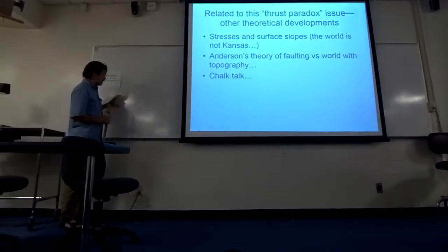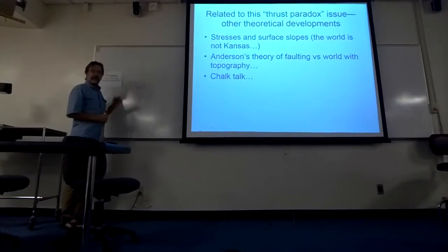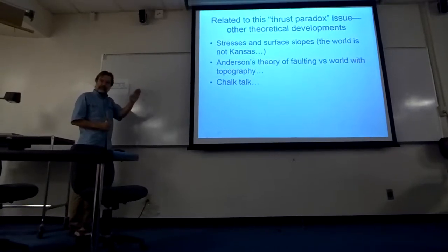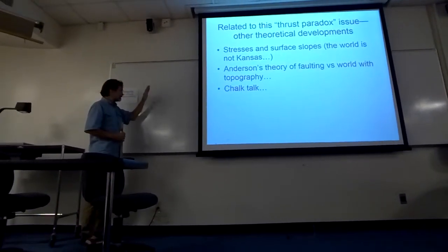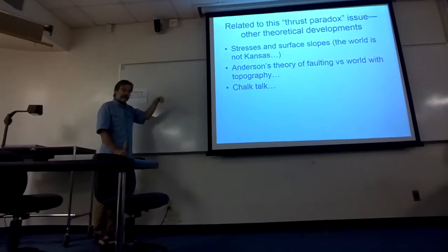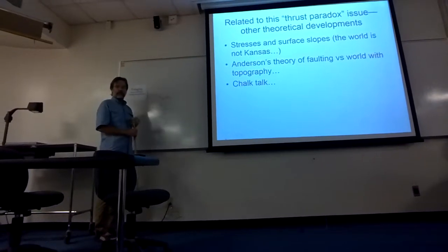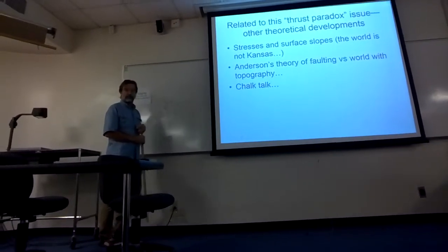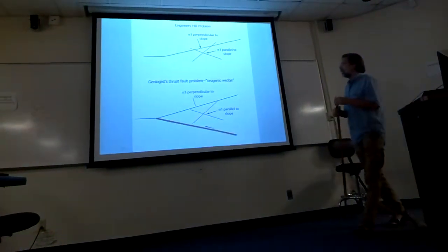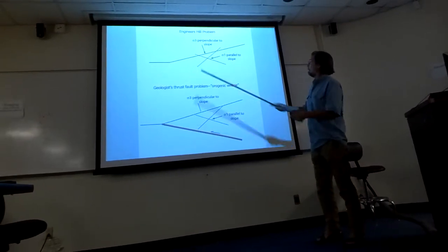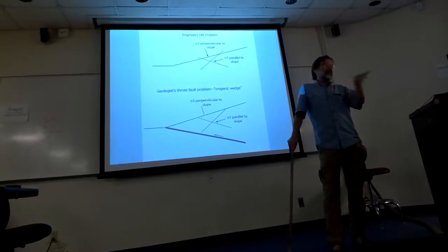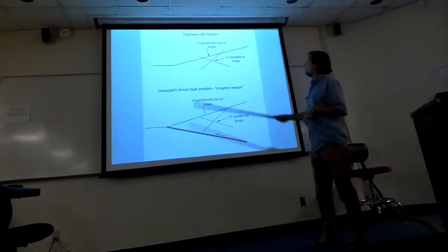One thing that we realized: when it's not flat, sigma v is no longer vertical either. So if you have a slope, the same kind of symmetry effect has to apply, that the principal stresses need to be, at least in the shallow part, perpendicular to the surface. But if the slope is there, then the principal stresses are also inclined. And therein lies the important part of that particular story, because the moment you make a surface slope, you're into the engineer's problem and not the lame problem of sliding a flat block across the surface. And the engineer's problem is this one.